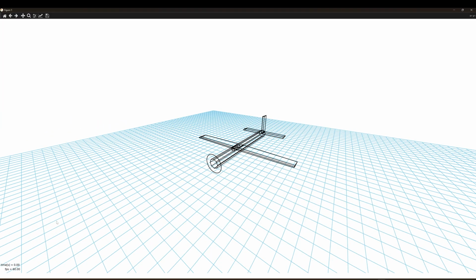As we'll show, this component build-up functionality is very useful inside of MAVRIK, especially for early design phases where detailed models of the vehicle aren't yet available. Today we're going to show that we need no aerodynamic information in order to get this vehicle to fly, just estimates on the overall size of the component. MAVRIK will estimate the aerodynamics and the mass properties of each of these components internally, but these models can be replaced with higher fidelity models such as CFD and wind tunnel when those become available.